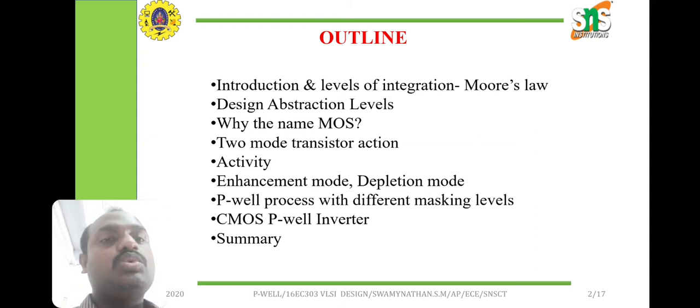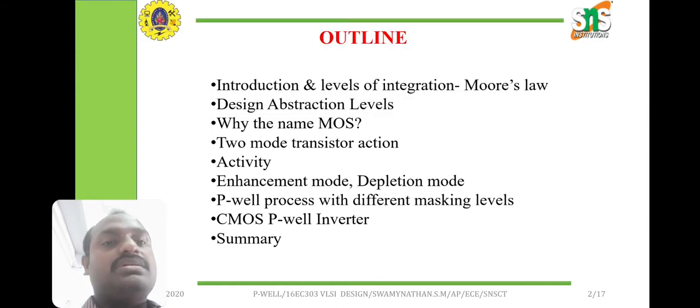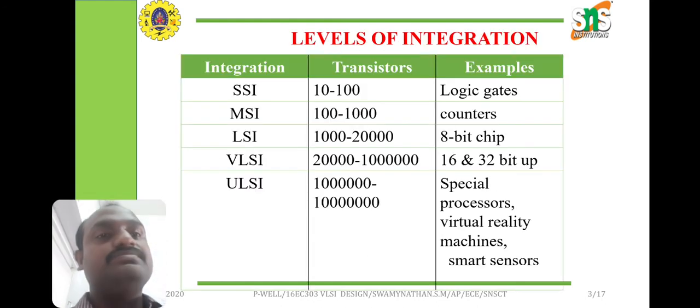Then, what are the two-mode transistor actions? Next, an activity. Two-mode action: enhancement mode and depletion mode. Then the p-well process with different masking levels. Next, using the p-well process, how can we design the CMOS p-well inverter? Next is the summary. So this is the outline of today's topic.